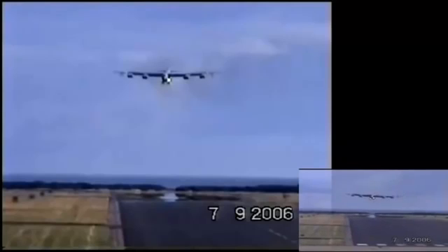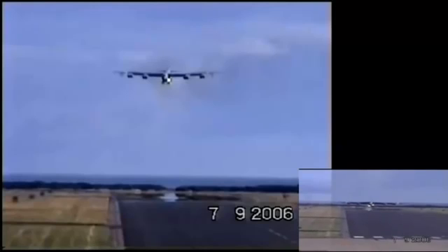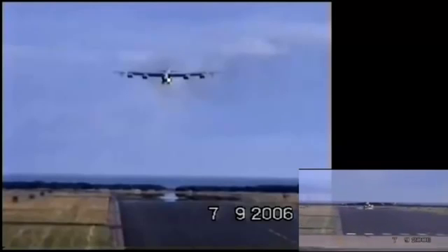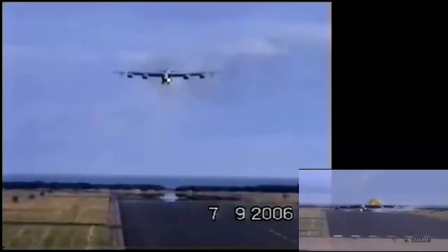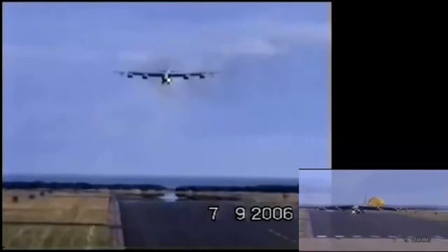So this is one of the only aircraft that is able to change the direction of the landing gear. So you can see it's actually landing a bit sideways. And as the picture goes on, you'll see better. But you see the aircraft is on the ground. You can see by the direction of the parachute where the wind is coming from. And it's more or less driving sideways, simply due to the landing gear, which can be directed in the correct direction.